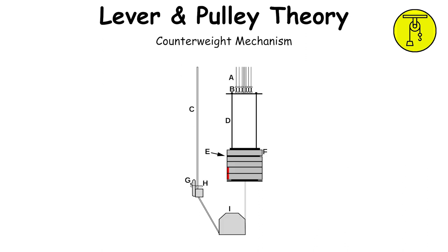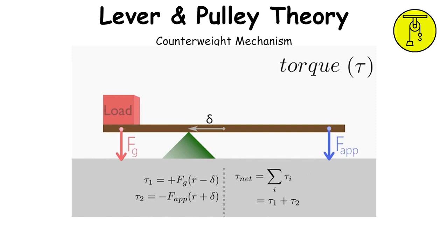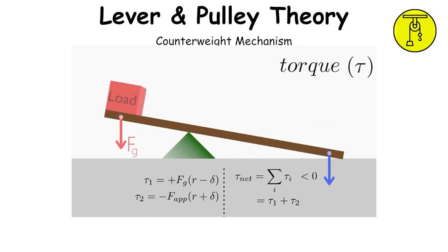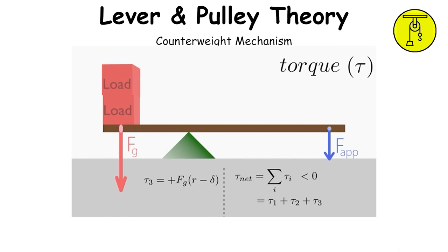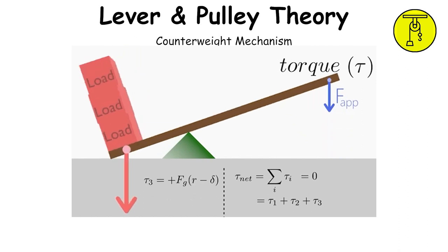Large, standard-sized blocks were used as counterweights to hoist the heavier granite beams. For example, to counterbalance a granite block of 50 tons, 8 limestone blocks of 5.6 tons each were used as counterweights. These counterweights were hauled up in the usual way and then used to lift the granite beams to the required height. Rope and pulley configuration.